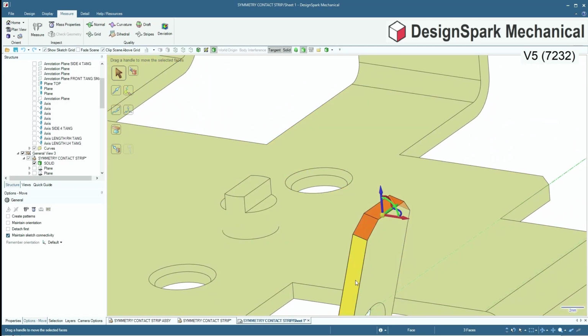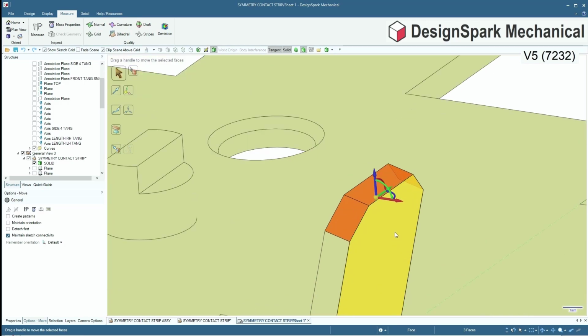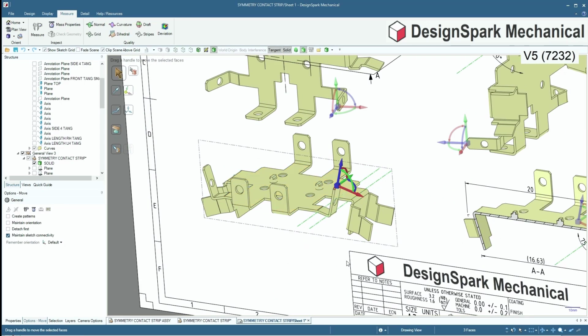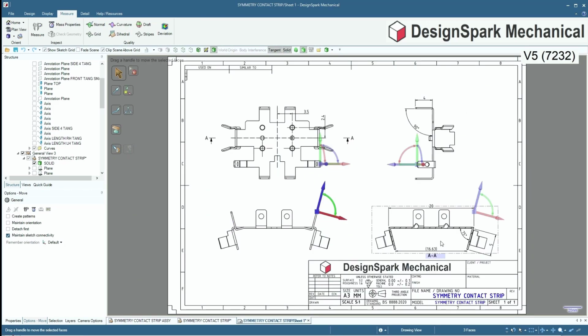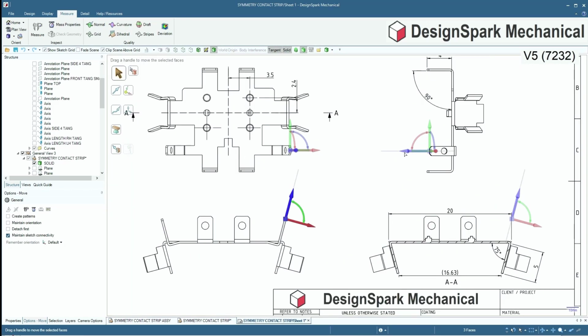Previously I made an alignment with this edge, and that produced a slightly skewed move tool, although it wasn't important for the move. However, if we now move this to the top face, you can see it orientate more in line with the directions of the face. It's actually the UV face directions, but let's not get into too much of that. If I go to my home view, you can now see that the phantom tools are now positioned as you might expect.